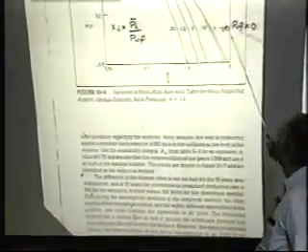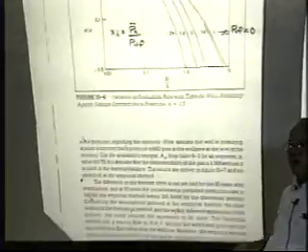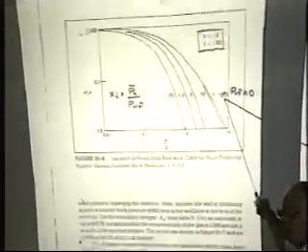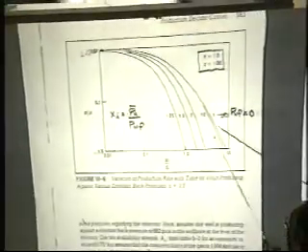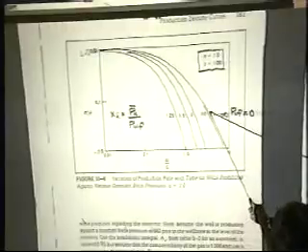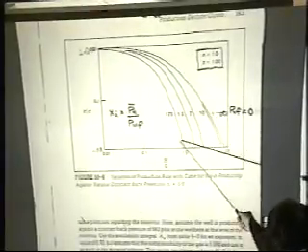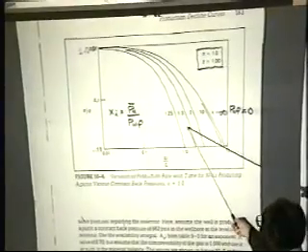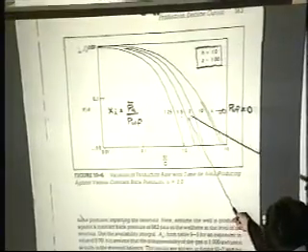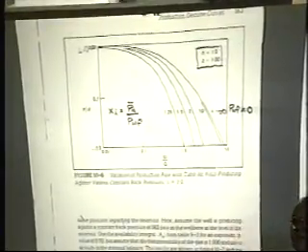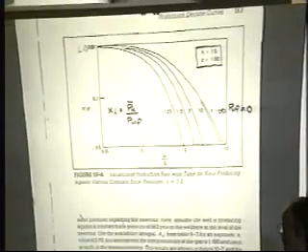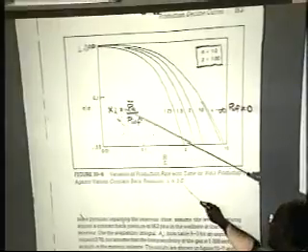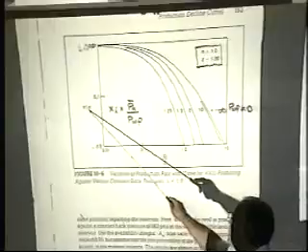This is for an N of 1. His ratio is the inverse of mine. He plots shut-in pressure over the flowing pressure, so the ratio out here of infinity would be my ratio of 0. And this would exactly be a B of 0.5, and you get to approach exponential decline. But he's got the back pressure actually built into these curves for a given slope, so that if you match on here, in the early days when you've got performance data against a higher line pressure, you could use this type of plot, and when you get your match points off the fit of the type curve, you can calculate Q sub i.